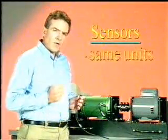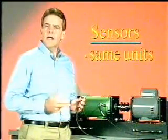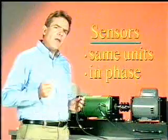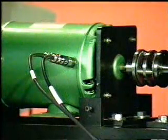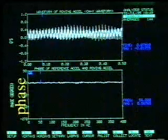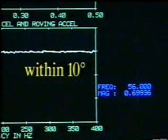First, the two sensors must be using the same units, such as Gs. Secondly, the sensors must be in phase. That is, they must read the same phase angle for a given point. To check for this, place the two sensors side by side on a machine and check the phase between the two. They should read exactly the same or within 10 degrees of each other.